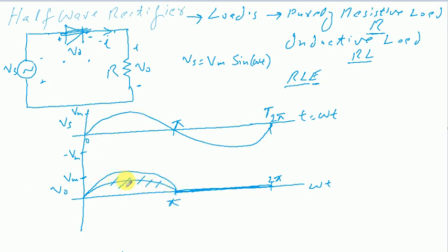Of course, that will be slightly lesser than the voltage in terms of magnitude, because that is the ratio of voltage to the load resistance. But the shape of the waveform will remain the same as the output voltage, and the output voltage will be exactly the same waveform, because we are considering an ideal diode. There will be no voltage drop across the ideal diode. So it will have the same value as the source voltage or the input voltage, and the current will be slightly lesser than that, but the waveform will remain the same.